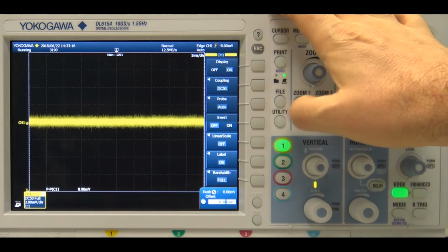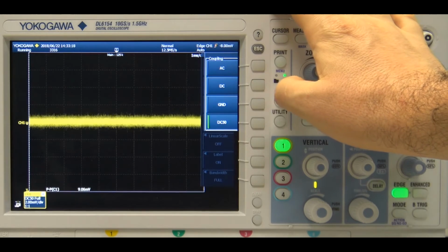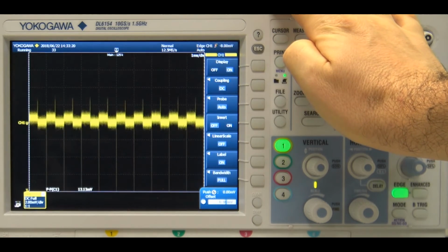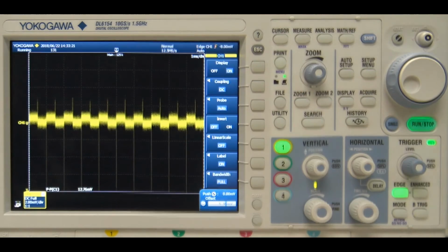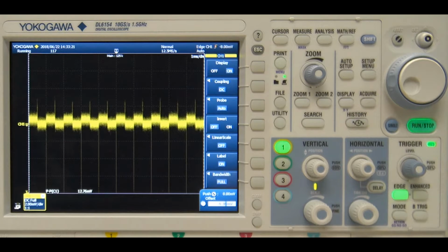Let us press the channel button, then I go to coupling and specify DC. Good. Things have improved quite a bit. I have simply changed the input impedance of my oscilloscope, which was 50 ohm. We are not displaying a radio frequency signal, but a square wave of 1 kHz frequency. The detector output has an impedance of about 1 kΩ at this frequency.